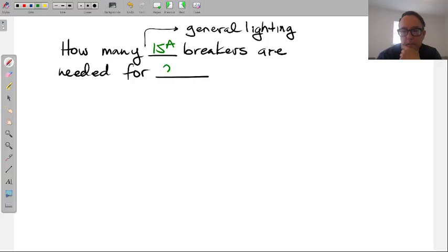Let's put a square footage here. 2,000 square feet. Again, it's represented like that. And so again, this is how the question gets asked for Article 210.11 and the VA per square foot. So we have to remember, and I'll put them here, the 3 VA per square foot.